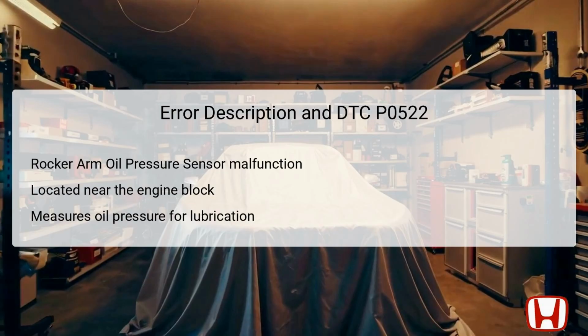The DTC P0522 indicates a circuit low voltage in the rocker arm oil pressure sensor. The rocker arm oil pressure sensor is a fundamental component that measures oil pressure, which lubricates the rockers and valves in an internal combustion engine. By being situated near the engine block, it has direct access to the critical oil flow. If this sensor reports low voltage, it signals to the engine control unit, ECU, that there may be a lack of adequate lubrication, potentially leading to engine damage.